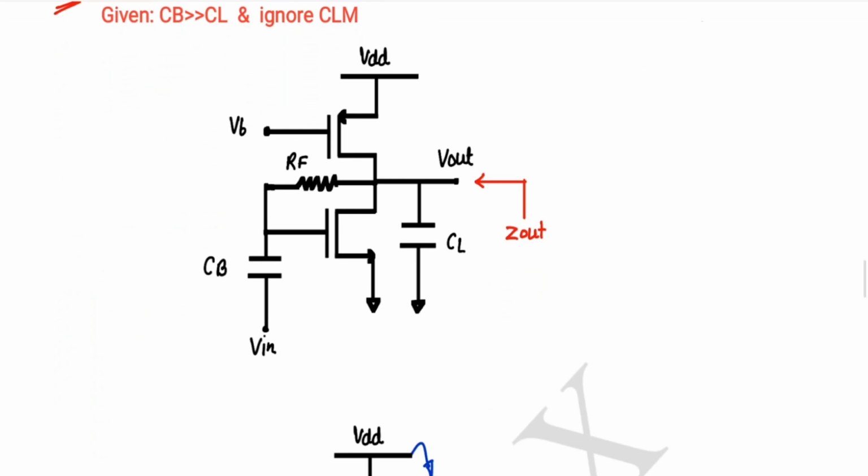There are two independent capacitances, so there will be two poles due to these capacitances, and there is one 0, so that path will give a 0, and you can apply KCLs for different cases. Since both pole locations are distant, you can treat them separately, one at a time. That way you can also calculate, and it will give the same result.